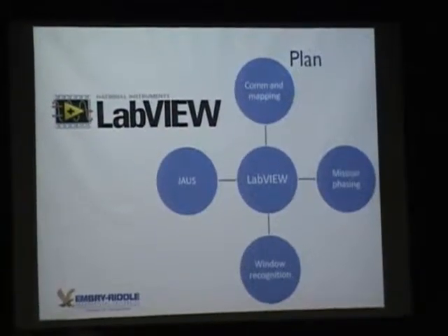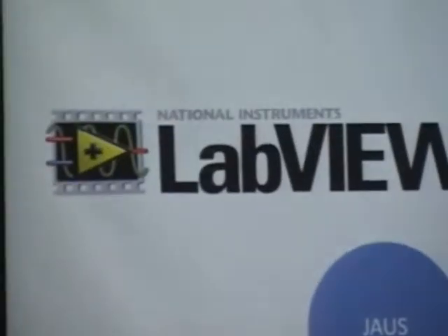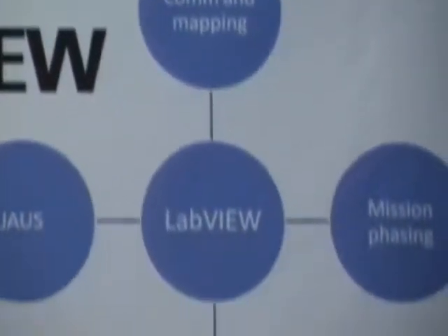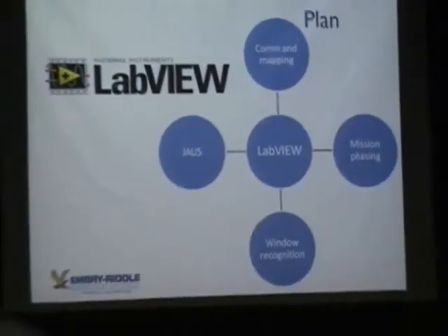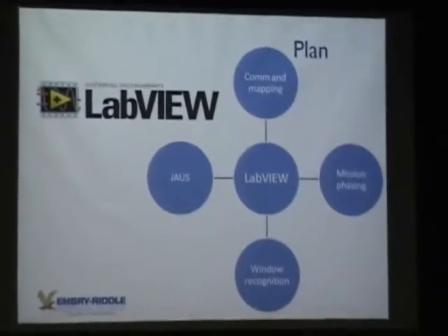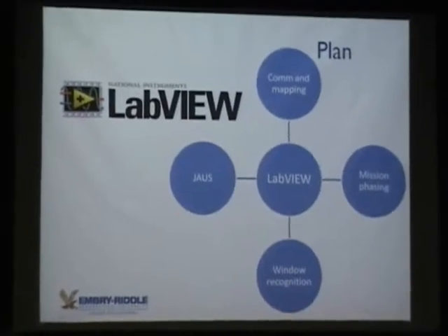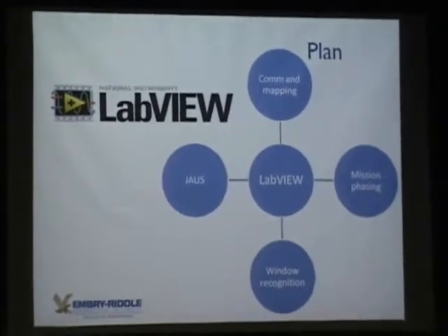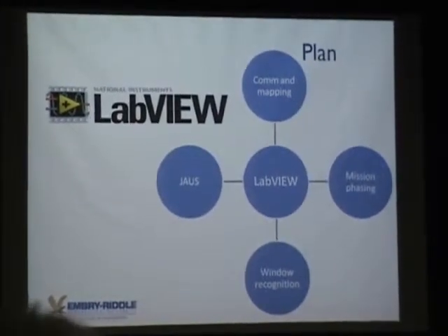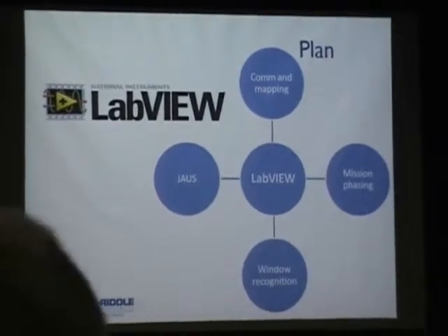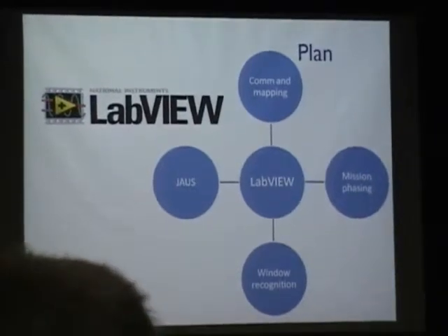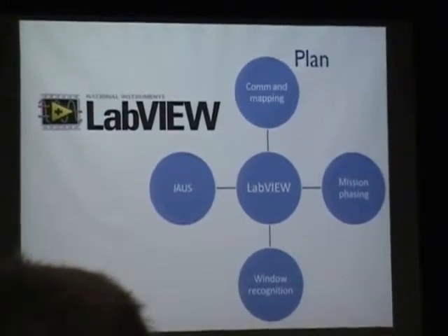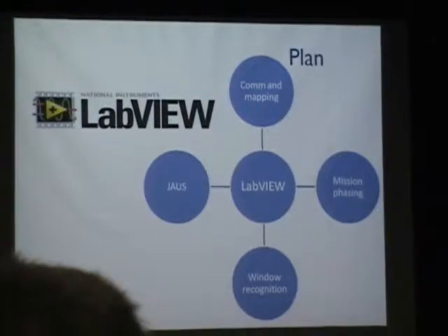Software-wise, there's a lot going on. Obviously, we're reading sensors, we're interpreting those sensors both for local reactive behaviors and for deliberative behaviors, and then we're also doing data link management and housekeeping as well as safety operations, and the uplink to an OCU via JAUS. That's a little bit much to handle on an Arduino. So what we do is we split that problem into low-level processing on board and high-level processing off-board in LabVIEW.